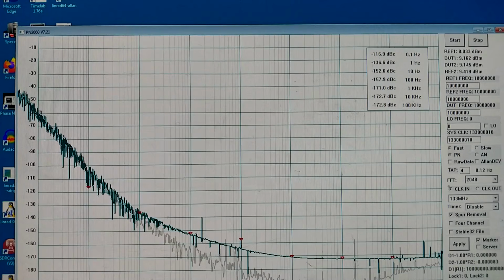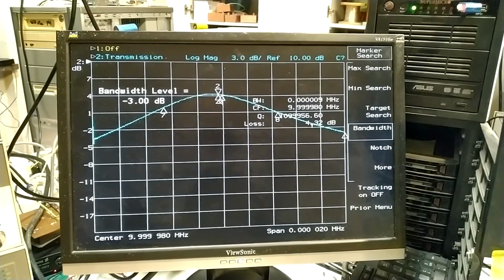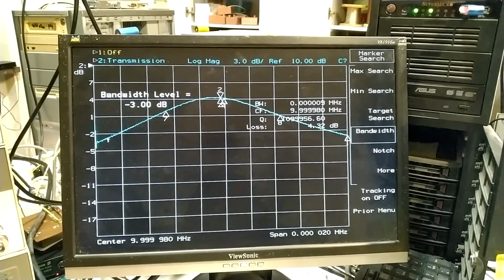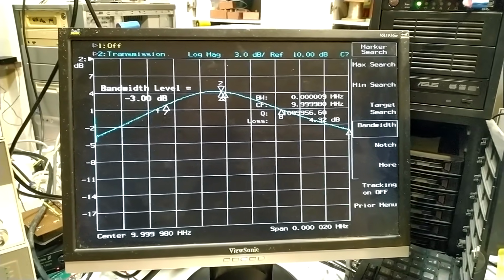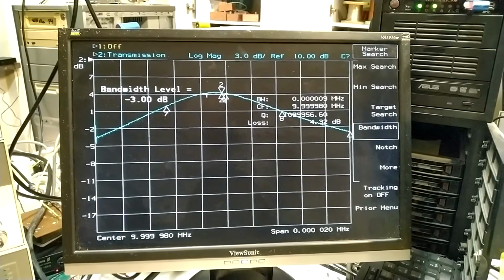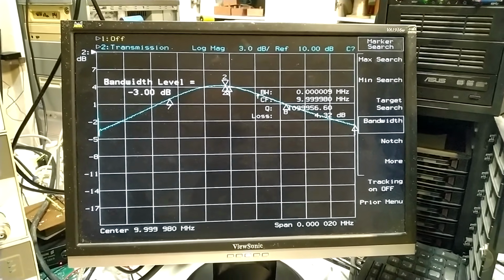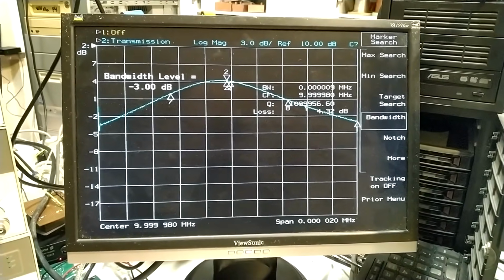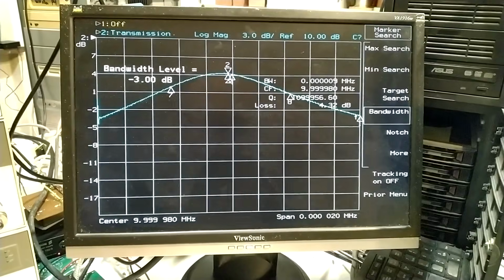On the other hand, I want to lower the frequency, which means putting a bigger capacitor across the crystal. That will probably make the impedance lower. So I will not change anything, but start to look at what happens when I change the frequency. With 100 pF parallel to the crystals and about 40 pF for the coupling capacitor, I get this frequency response. It is now on the frequency of the shifted rubidium oscillator.